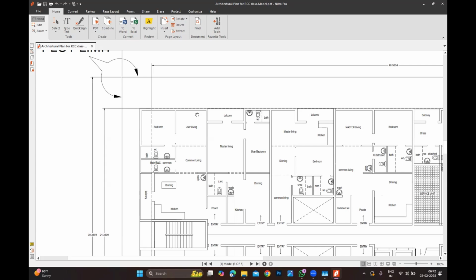What happened? Till the draft detailed design stage, the authority had given approval. How can you go back and change the entire thing? What is the problem that has happened? The guy who placed the columns from the basement, the entire floor is transferred. None of the columns is starting from the basement. All the columns you force to stop at the ground floor, and from the ground floor you need to introduce all the transfer beams.